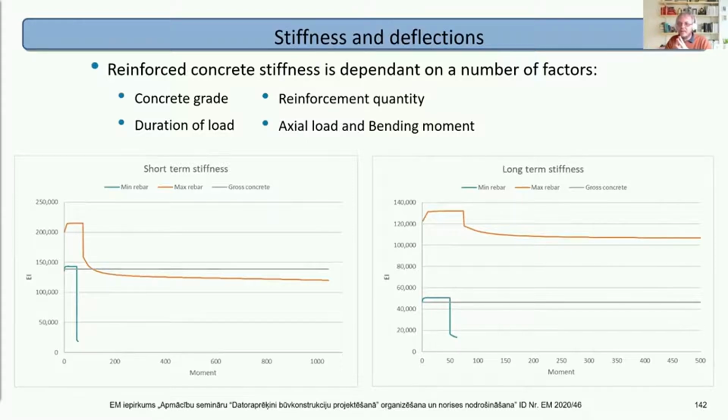So yeah, definitely if you need to understand the deflections in detail, then you do need to take the reinforcement into account, but also bear in mind the difference in stiffness can also redistribute the moments. So ideally speaking, you have a simple option: the Young's modulus is halved, whatever, it's near enough.